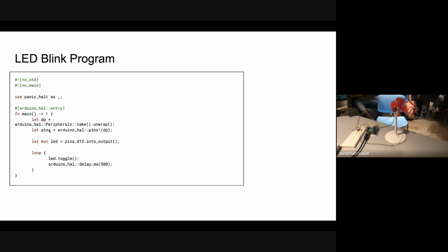So our first line is that we've got a bunch of these peripherals. Of course, Rust, as we know, is a safe language. So the peripherals are all put into the structs that we have to take, because of course these pins are essentially the equivalent of global variables, because the pin is a physical object, and for each pin there's only one, and it has a state. It's either high, low, or it's going to be in that high impedance mode, which is what you use for reading. You've got a list of pins because there may be other peripherals that are not pins associated with this.